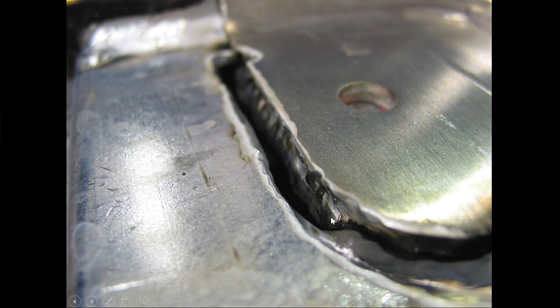Now, skilled people with TIG welding can look at me and tell me all day long, and MIG welding people, "Bob, I could fill that." I don't want you to fill that. That's the point. Your quality program does not want you to fill that because that weld has no integrity whatsoever. If they have a field condition and that cradle comes back, or God forbid if there's an accident, that's going to hold nothing if you bridge it with a little bit of 4043 or 5356, and try to fill it with a bit of a bridge.